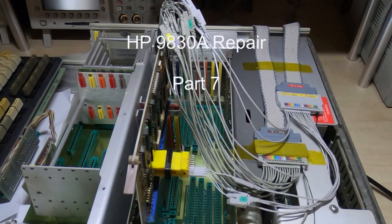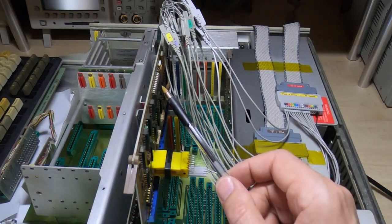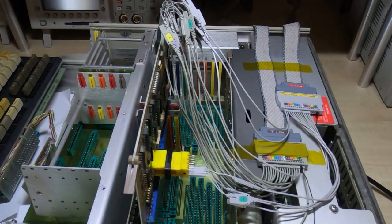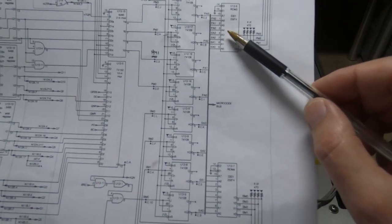This is part 7 in a series of videos in which I'm attempting to repair an HP9830A desktop calculator. In the previous video we traced a potential fault to this card. This is one of the CPU cards and it's the microcode generator. And what seemed to be happening is that following a reset, we were indeed resetting to the correct address.